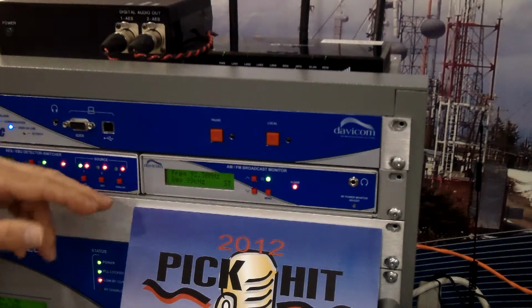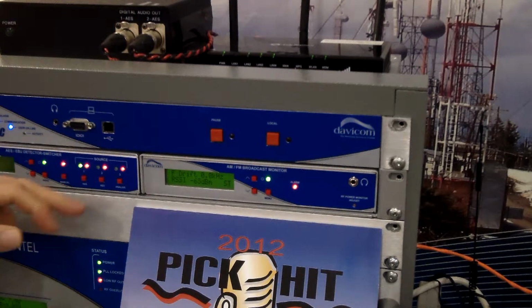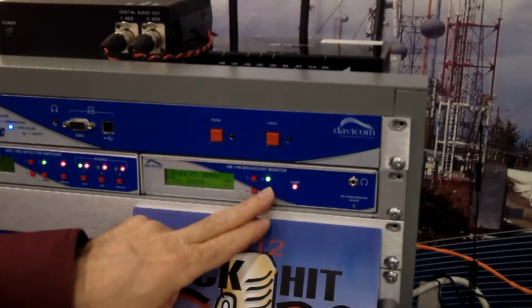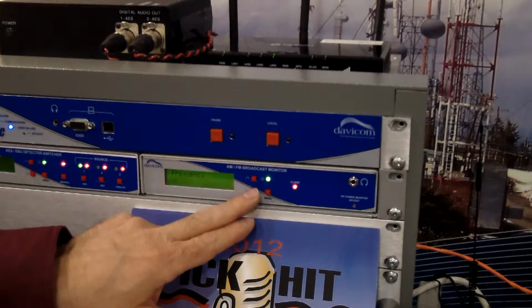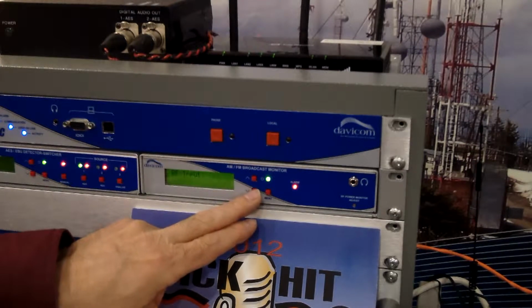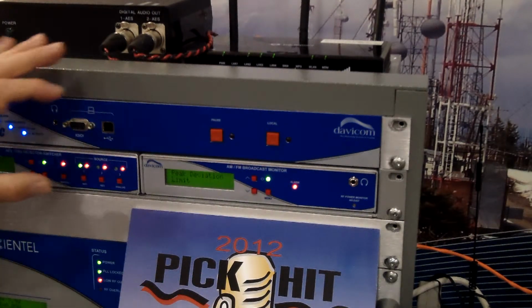So you can measure the RF power level either off the air or through a coupler when you're connected at the site. The menu allows you to select different settings like tuning steps, the frequency, the alarm display. This will display the active alarms in the unit, the RF input level, audio levels, and so on. So you can cycle through all of that and configure the unit locally at the site.